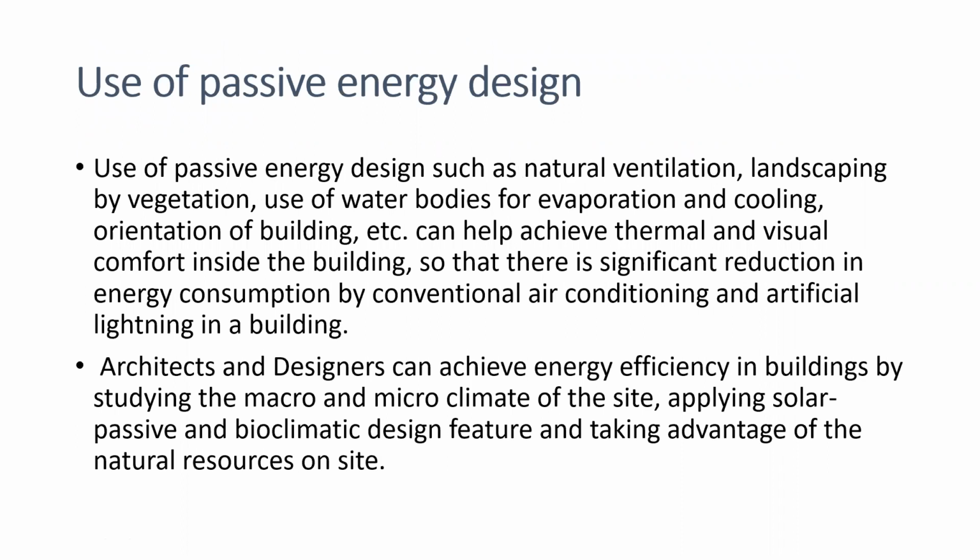Use of passive energy designs such as natural ventilation, landscaping by vegetation, use of water bodies for evaporation and cooling, and orientation of the building can help to achieve thermal and visual comfort inside the building, so that there is significant reduction in energy consumption by conventional air conditioning and artificial lighting in a building.